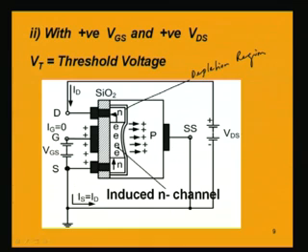So, the drain current is equal to the source current, Is equal to ID, and we also notice that Ig is equal to 0. Although there is a voltage between gate and source, the current at the gate terminal Ig is 0, because we have seen here that there is a layer of insulating material between the gate terminal and the substrate.